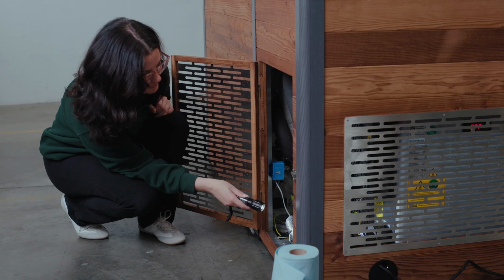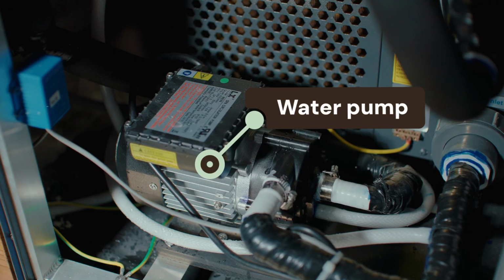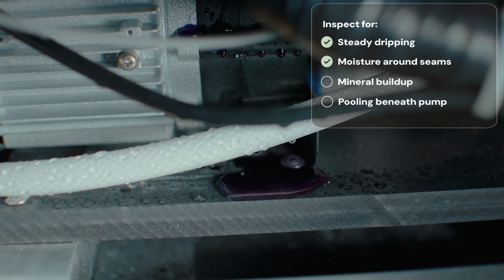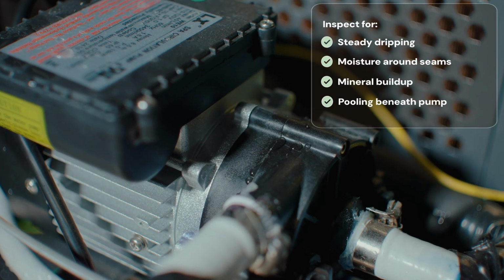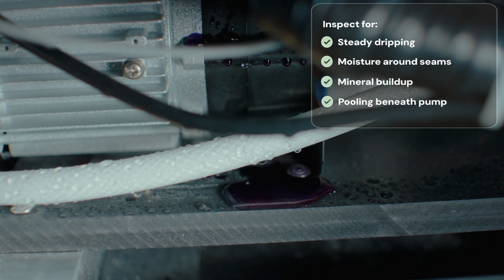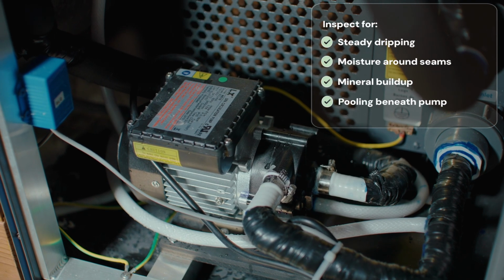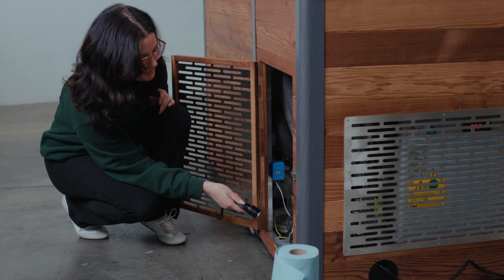While water pump leaks are not especially common, they can occur from failed seals or damaged components. Inspect the pump assembly carefully, paying close attention to seams, unions, and areas showing active moisture or mineral buildup. If the source of the leak is confirmed to be within the pump body or internal assembly, the full water pump will typically need to be replaced. For electrical or pump-related repairs, professional assistance from a licensed plumber or qualified service technician may be recommended.